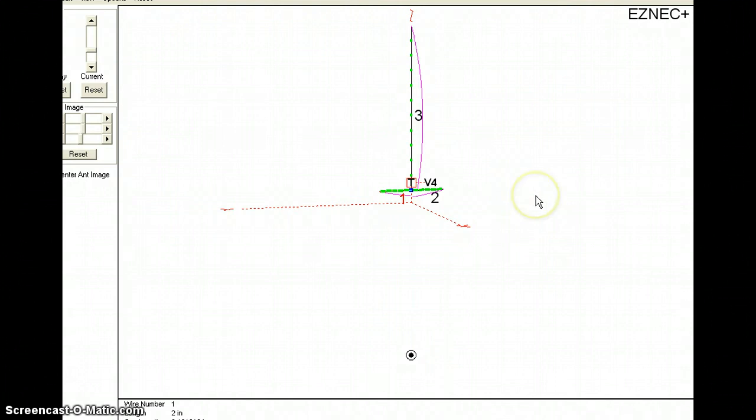We're going to model this antenna by a ground plane that's essentially 4 inches and a monopole that is 8 inches. They're tied together at this point, and we're going to feed them at this point. One of the neat advantages of this program is that we can sweep this antenna over a range of frequencies, and today we're going to sweep it from 400 megs to 500 megs. I've done that, and I've recorded that on a PowerPoint slide.